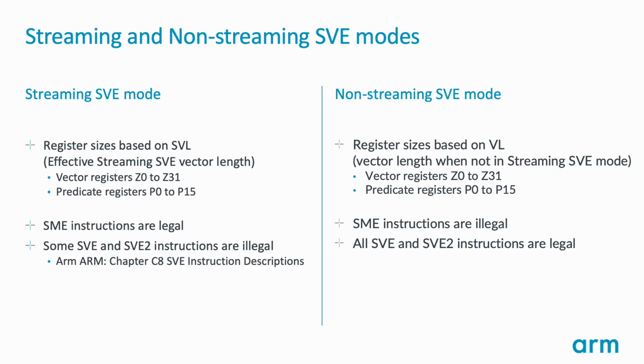So the complete ZA vector array width and the Z vector register width will be the same, and the support for SVE2 instructions enables effectively using these registers to load from memory, store the contents back to memory, manipulate the data in the ZA array, move it to different vector registers, perform the outer product of the matrix computation, and directly be able to store it in the ZA storage.